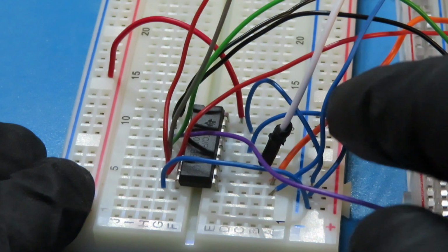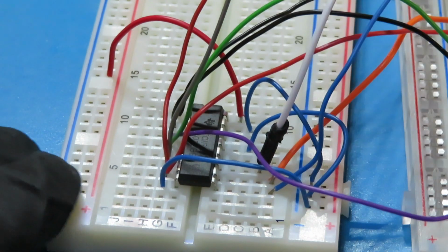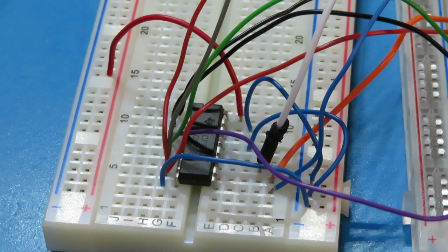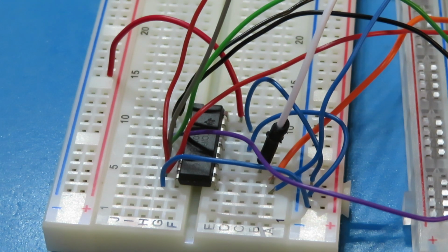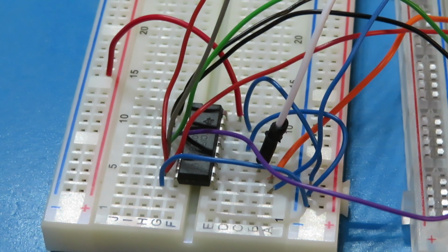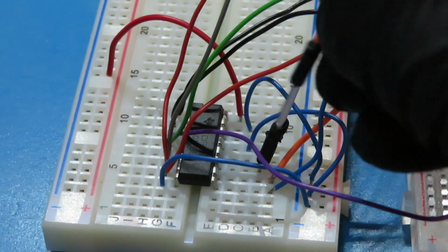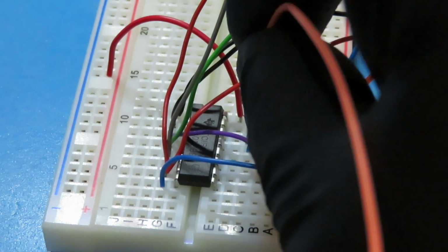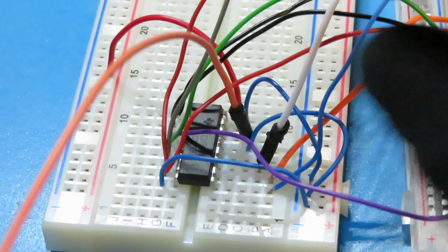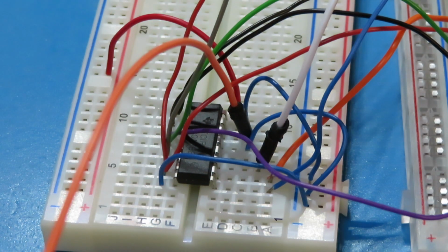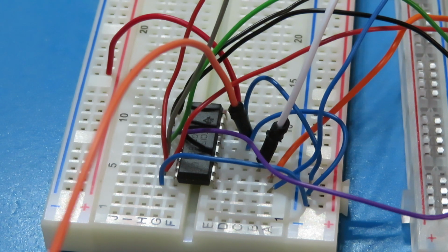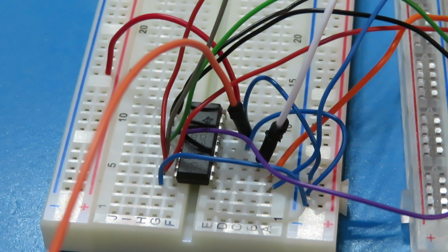Here I have everything wired up according to the schematic. So let's go ahead and hook up one more jump wire in pin 14, that's our clock pin. We still have to figure out a way to give a clock signal to this IC, but for a while we can hook up this pin to the negative rail of our breadboard, and in this way we're gonna check if everything's working fine so far.